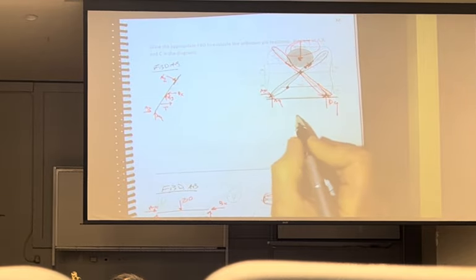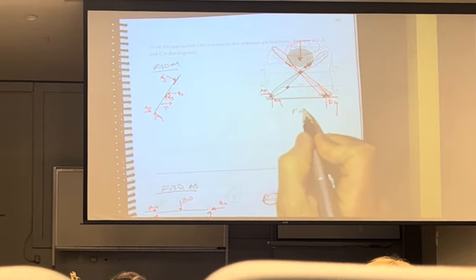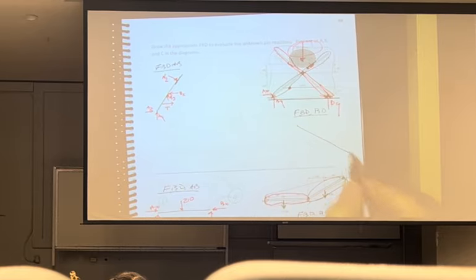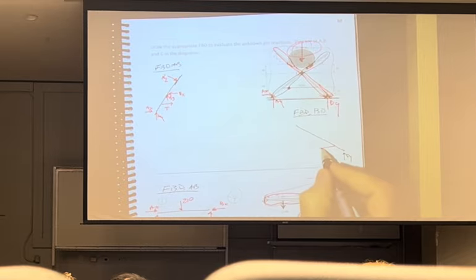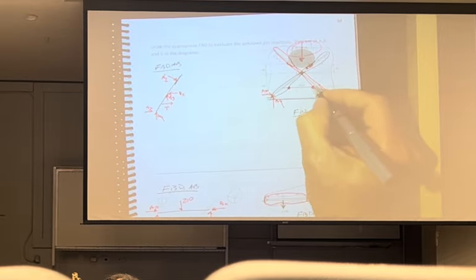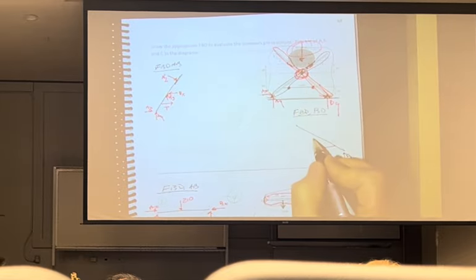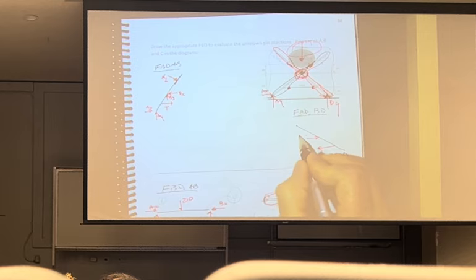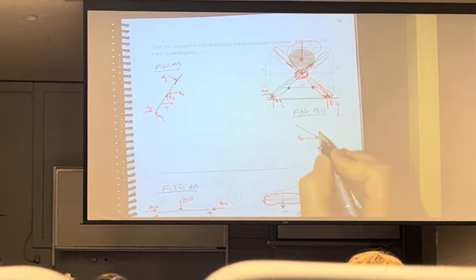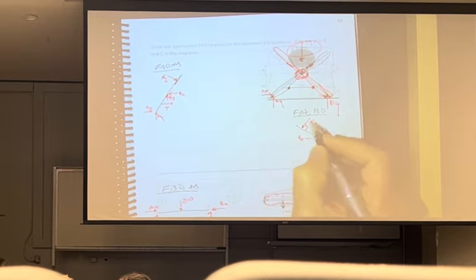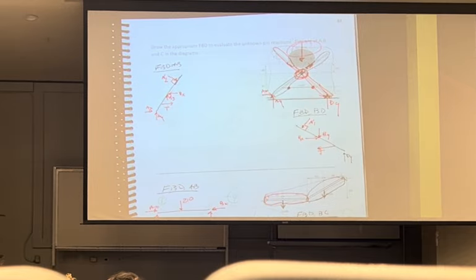And over here, I'm going to draw a free body diagram of BD. That looks like this. I would have a DY. I'd have a cable tension T because I touched that cable right there. I got to show B. Well, that has to be opposite of what I drew already. And then I have to have an N1. The normal forces are always going to be perpendicular.